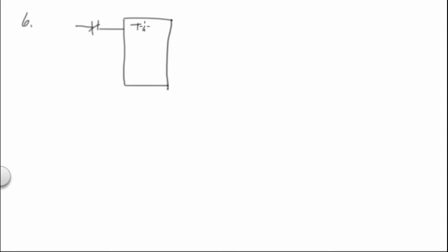So TON, that turns itself off. This would be the done bit, let's call this the coil out here would be A. When it's done, the not of A. And this would be a TON timer. And let's call it timer 1, okay?